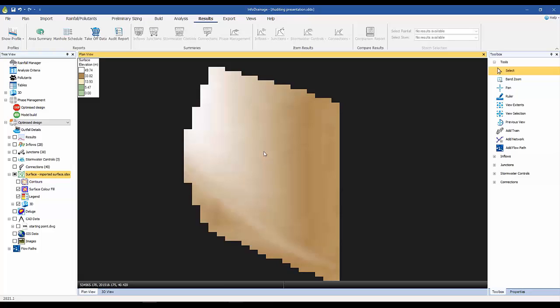In other locations, maybe you're operating in a particular part of the country that doesn't have that data freely available, so it may be necessary to commission your own survey. It can also import that data. Thirdly, I'd give a shout out here for our XPSite 3D road design package. In that you design the roads, design the finished floor levels for the properties, design any other earthworks. Once you've completed your design in XPSite 3D, you can then export the final surface from there, and then that can be imported into InfoDrainage, and you use that as the basis of your flooding assessment.